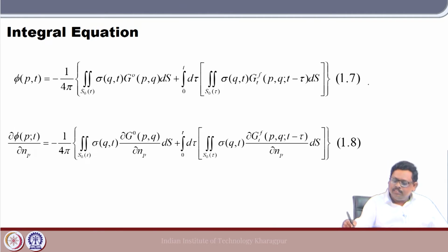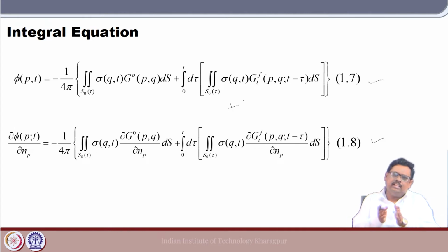Now, here remember that equations 1.7 and 1.8 are only for the floating structure. In case of a forward moving body, there should be another term with this, about the water line, that is absent here. It is just one more term. However, this is the main integral equation for the floating body. Let us discuss this whole exercise for the floating body problem only. Then you need to differentiate with respect to the normal. So from 1.7 you get 1.8.